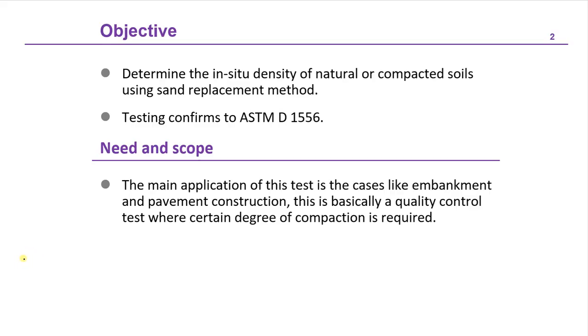In the standard Proctor test we get gamma d maximum and the optimum water content. So these are our reference values, and they come from the lab. We try to achieve these densities in the field. If we can attain the same density, it will be 100% compaction, but mostly we can get up to 95 or 98% compaction. It depends on the requirement of the design.